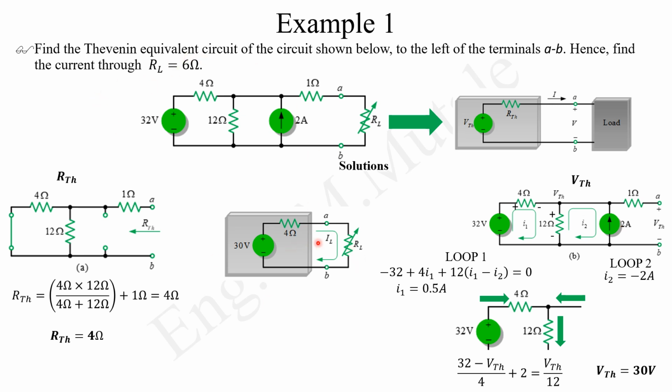Or we know this is a closed loop. You can find the total resistance, which is basically this one and this one. That total resistance, when it divides into the voltage, you are going to have the circulating current in there, which is this one. So IL, or the circulating current in there, is basically the voltage in here divided by the summation of the oppositions, which is this resistance and the resistance there. So you have the Thevenin resistance, which is this one, and the load resistance here, which is this one, which was given in the question. Once we do our substitution there, you are going to have our load current as 3 amps.